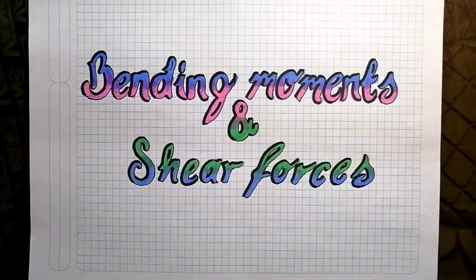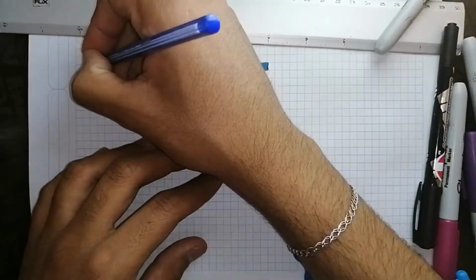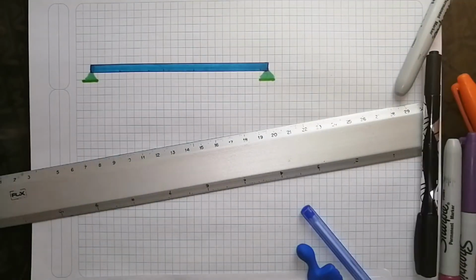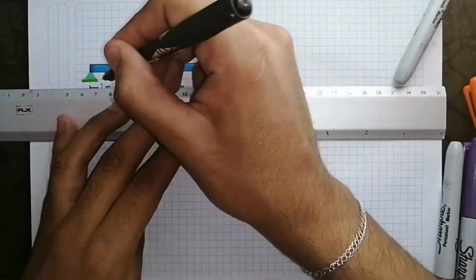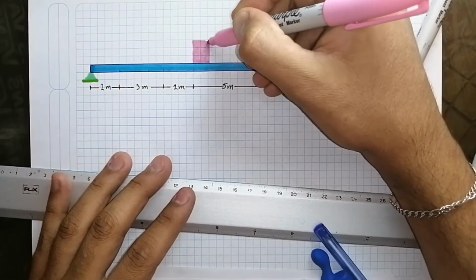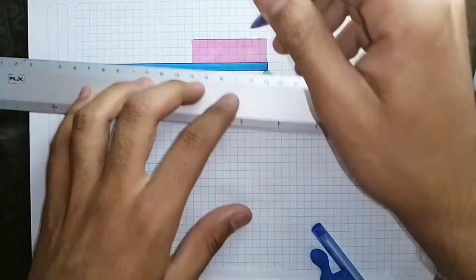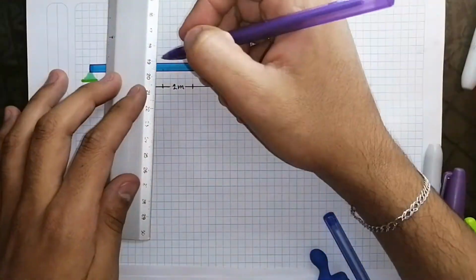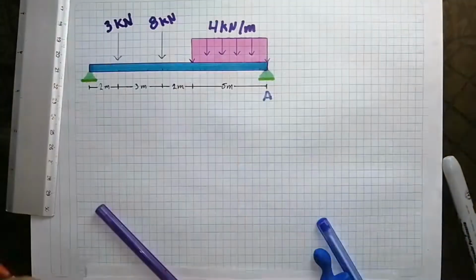Well, first we need to know what is shear and bending. Shear force occurs when two parallel forces act out of alignment with each other, and bending moments are rotational forces within the beam that cause bending at any point within a beam. The bending moment is the sum of each external force multiplied by the distance that is perpendicular to the direction of the force.